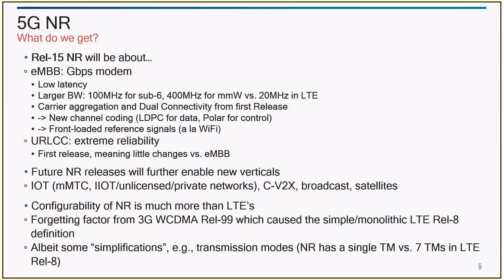What it also tries to achieve is a single transmission mode, unlike LTE, where release 8 had 7 transmission modes, and by now we have up to TM10. But NR targets to have only one transmission mode throughout, or at least for release 15, until some compelling reason comes up for release 16.